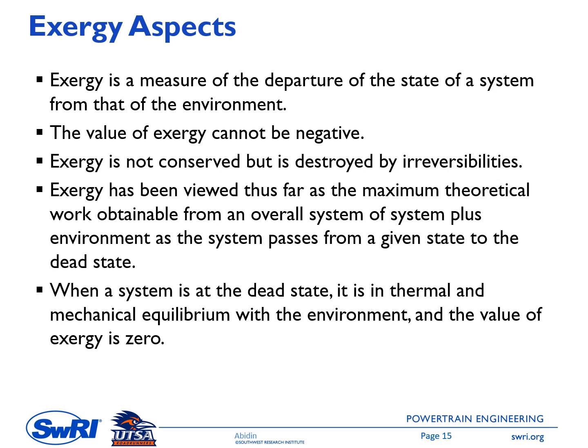Okay. Number 3, exergy is not conserved. Okay, exergy is not conserved, but it is destroyed by irreversibilities. So you will see later on that although the energy is constant, the exergy decreases. Okay, so if you remember from the very first feature in this chapter, where I have an initial system consisting of 100% fuel inside the tank and then surrounded by air, and then at the end I don't have fuel at all, and then the surrounding air is just slightly warm. We can see, or we can calculate later on, that the energy is constant but the exergy decreases.